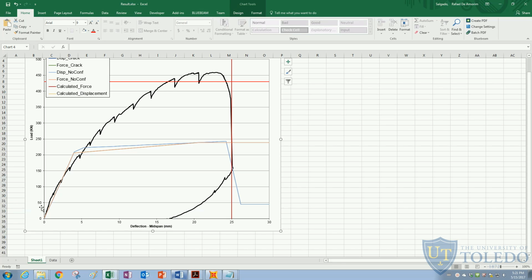So to try to fix all these problems we have with very conservative default shear hinge calculations, and our shear hinge not considering anything of our stirrups layout, we can do custom shear hinges, where we will go into the shear hinge window that I showed before, and we will edit those points that the force-displacement of the shear hinge curve follows. We will do that in a future video and not in this one, but this is something we can do to get a better response on shear critical elements.